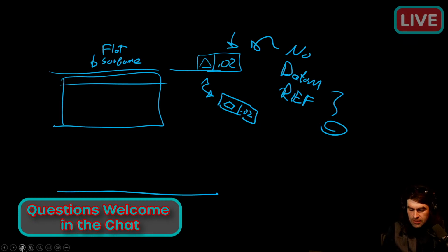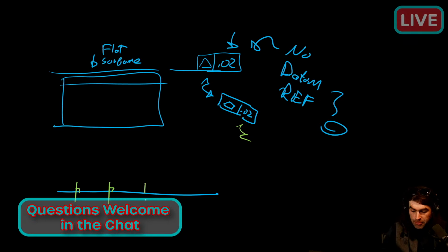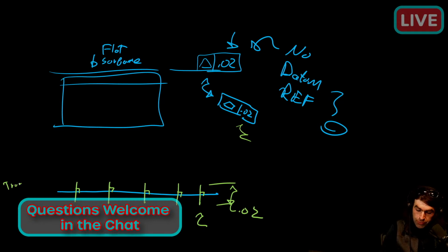So the tolerance zone for profile is defined different than flatness, right? So flatness is two parallel planes. The minimum size is the actual, and the maximum size or whatever is what's in the feature control frame. With profile, it's defined different, right? It's defined as being perpendicular at all points. So what I'm drawing is little lines here that are 0.02 long. They're perpendicular to our true profile,